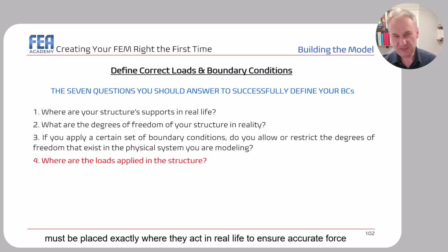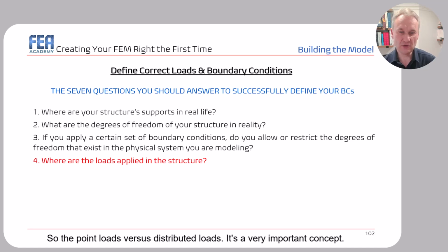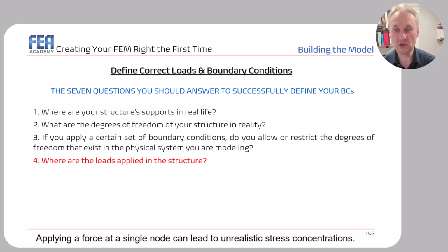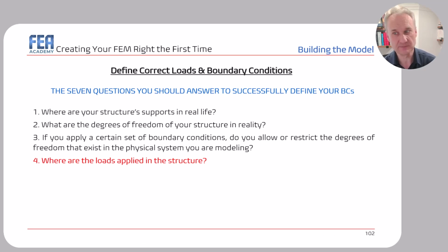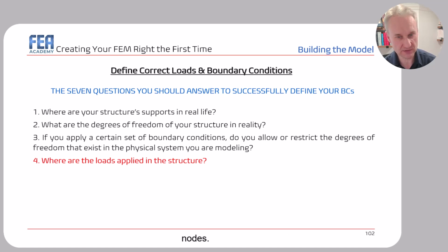The fourth question is, where are the loads applied in the structure? The loads must be placed exactly where they act in real life to ensure accurate force transmission and stress distribution. So point loads versus distributed loads is a very important concept. Applying a force at a single node can lead to unrealistic stress concentrations. It may be better to apply the load over a surface or distribute it among multiple nodes.